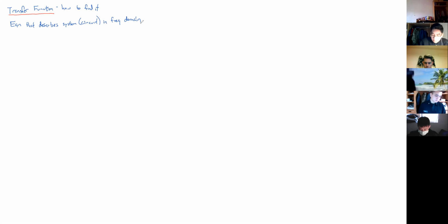So we've got a bunch of different ways to describe what a circuit is. One way is the circuit itself. Another way is its impulse response. We feed the circuit an impulse. Whatever we get out, we call that its impulse response. And just with that one waveform, that one h of t, we can now figure out what its response is to any input waveform by convolving. But this is a new way to describe what our system is.